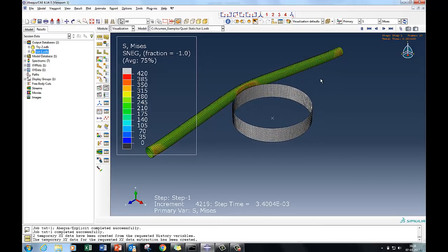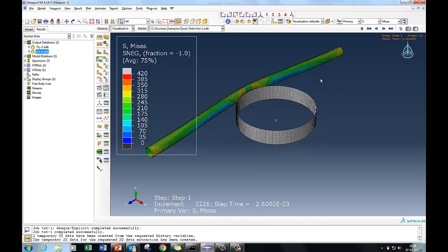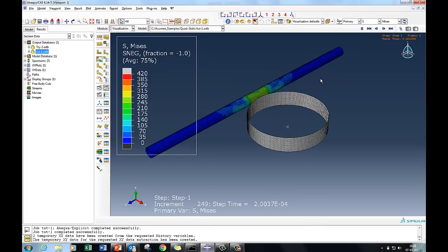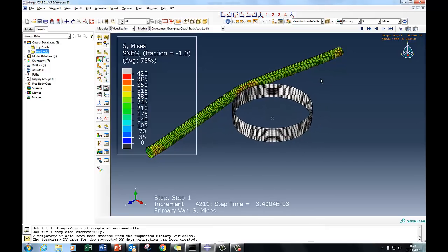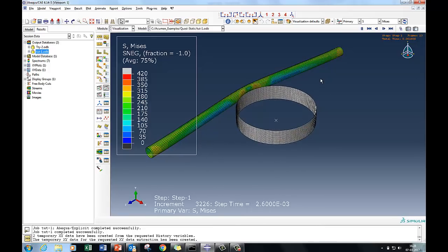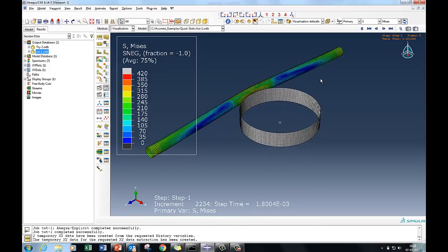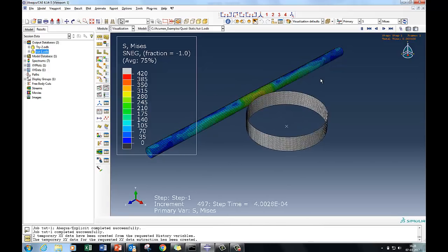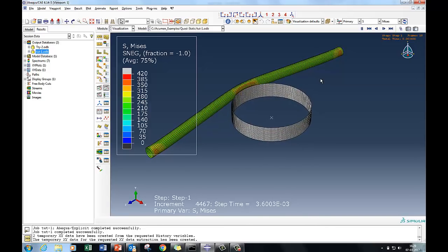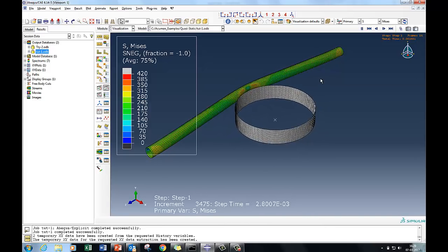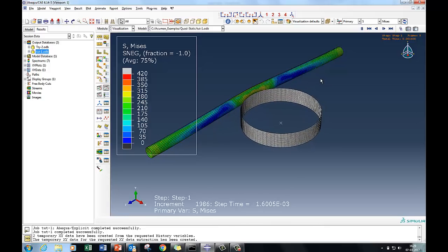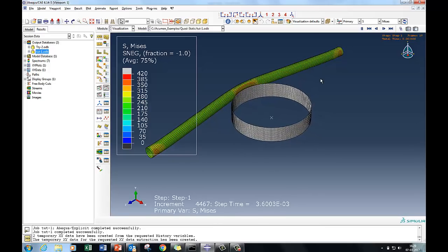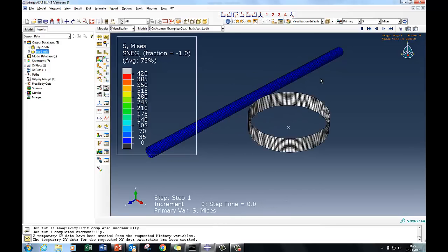And we have set all this model, and you can try out a few more iterations, like changing the total time even further, increasing from 0.004 to some more number, and see what the results are. In my view, if you increase this load application time further, from 0.004 to maybe 1 second, or sorry, 0.5 second, you can have more stable results. So this kind of iterations you can carry out, and make sure that your runtime remains less and still you get quality results. So that's the whole objective of the further iterations.